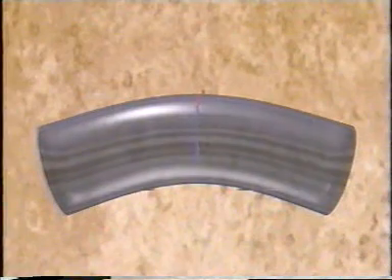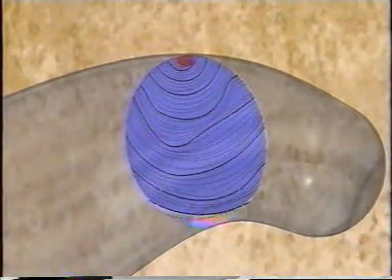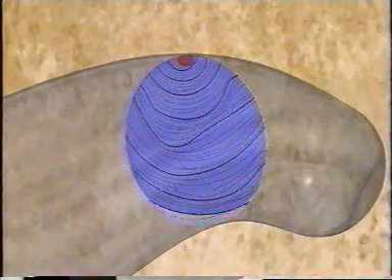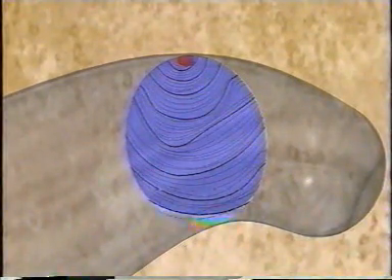On the microscopic scale, the most important feature of the fatigue process is the nucleation of one or more cracks under the influence of reversed stresses that exceed the flow stress. Subsequently, fatigue cracks propagate by a series of opening and closing motions at the tip of the crack, producing the striations which form within the grains.